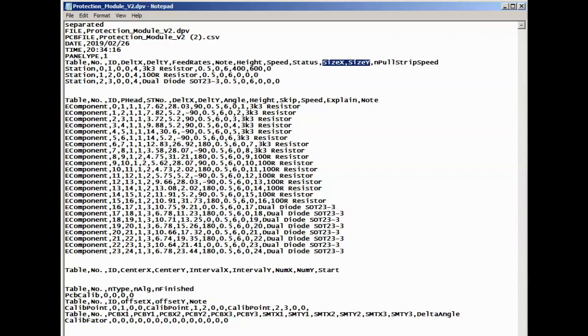When I say they don't make sense, this information is used by the pick and place machine by the up-facing camera. So when the machine picks a component, it goes to the up-facing camera if you have that enabled for the particular job, and it looks at the component. Not only does it make sure that there is a component there, but it checks its orientation, and it also optionally checks the size of the component to make sure you've got the right feeder in the right slot.